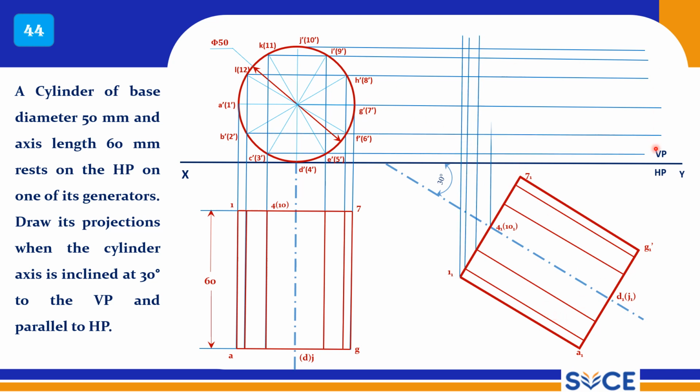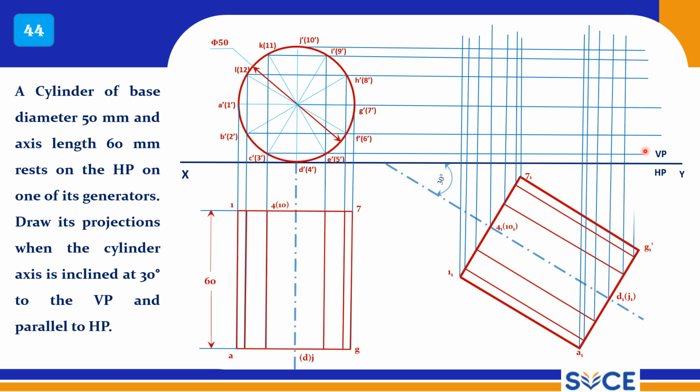This is the final front view we are getting here, and the points you mark here, all 12 points on both sides, totally 24 points you need to mark. You do it patiently, right? It is very important, so that you will get a very fine curve, and that will fetch you very good marks, right? So outermost points you connect with a thick arc, and 4 to D you connect with a thick line, and D to G, right, you connect with the thick line up to J, thick arc, and then draw the straight line.